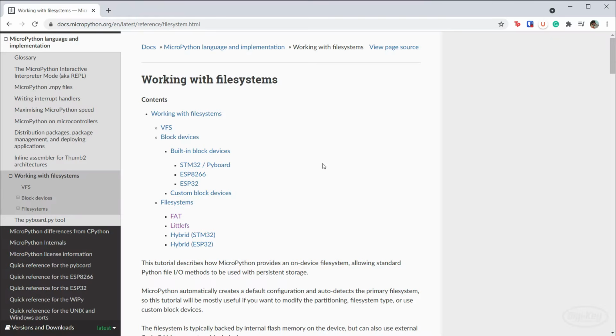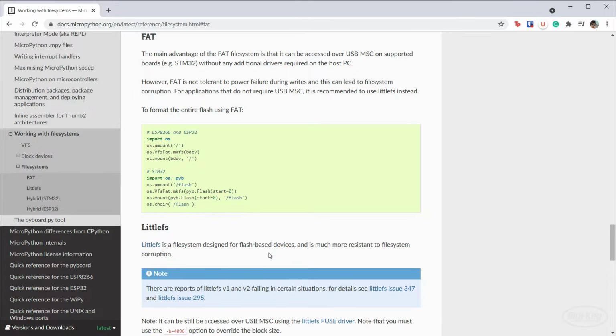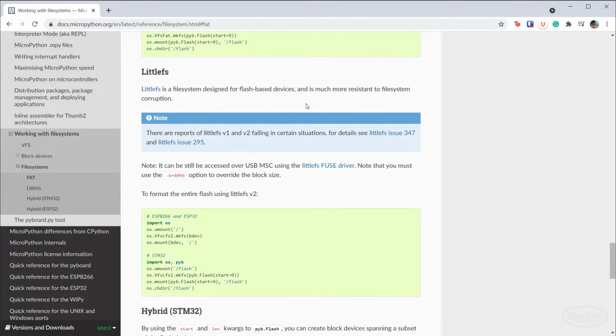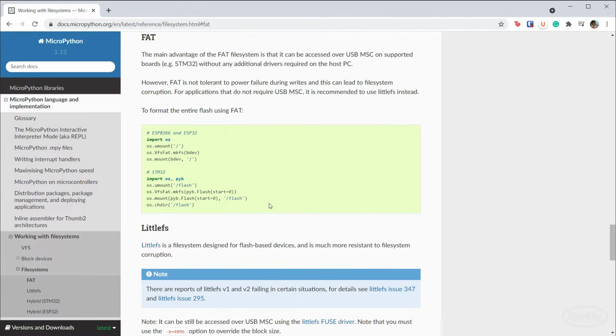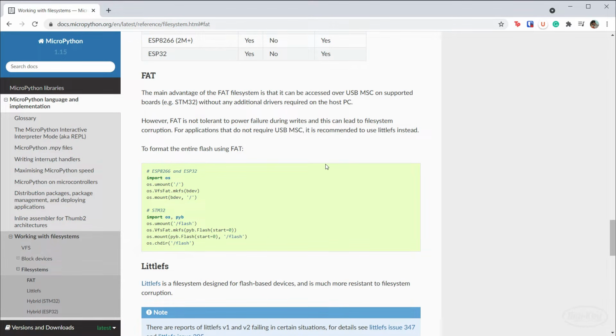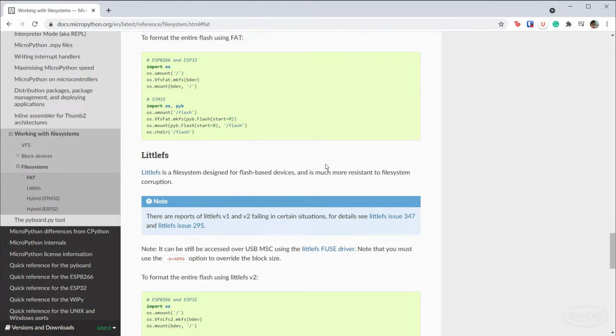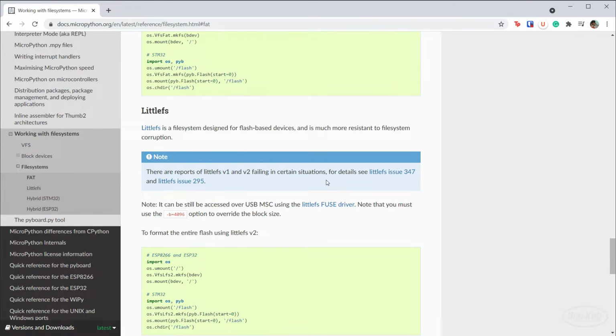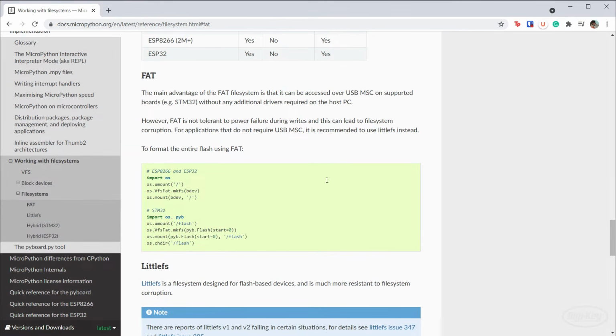MicroPython has some built-in libraries for working with SD cards and file systems. The Pico version of MicroPython, known as the RP2 port, supports LittleFS and FatFS out of the box. LittleFS was created specifically for embedded projects. The libraries are usually smaller than FAT, and it's resistant to corruption on power loss. With FAT, you can often corrupt the whole drive if you disconnect power before finishing a write. However, I've read that LittleFS may still have some bugs as it's relatively new, so use it at your own risk. FAT is tried and true, so let's go with that for now.